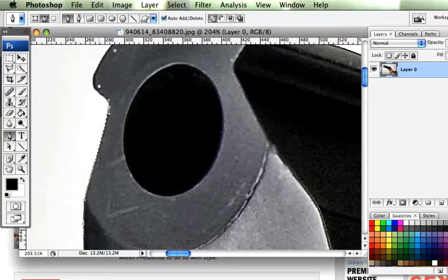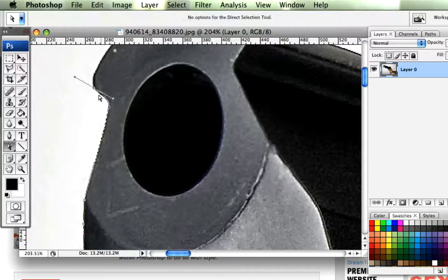And I'm just clicking and dragging, okay? You're just watching, keeping an eye on that and seeing where the bend comes. So here, I've got a nice big bend to this point, so I can just pull that out and move that in. If you press A on the keyboard, it selects this white mouse pointer, which is the direct selection tool. Again, I can now move that point into place in case I'm just off, which I was there.